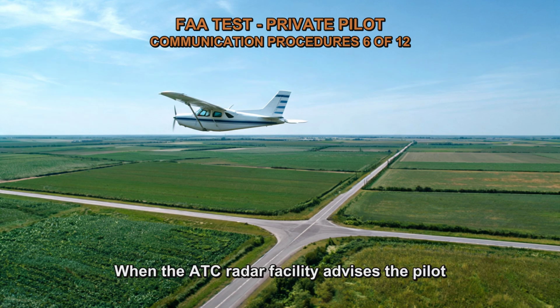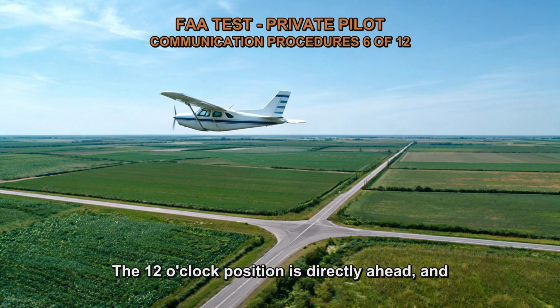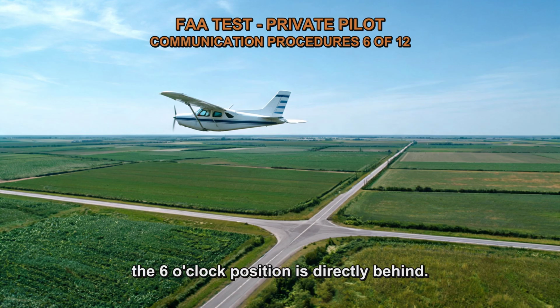When the ATC radar facility advises the pilot of traffic at 10 o'clock, it indicates the relative position of the traffic in relation to the aircraft's heading. In this case, the pilot is flying on a heading of 360 degrees north, and the traffic is reported to be at 10 o'clock. You can imagine a clock face overlaying the pilot's view. The 12 o'clock position is directly ahead, and the 6 o'clock position is directly behind. The 10 o'clock position is to the left of the pilot's heading.